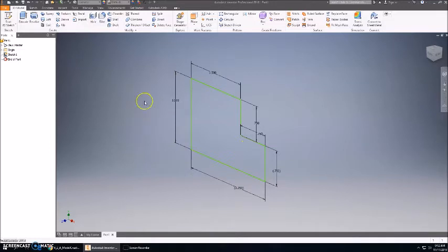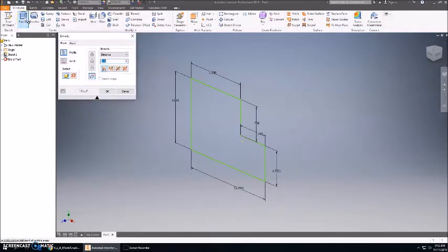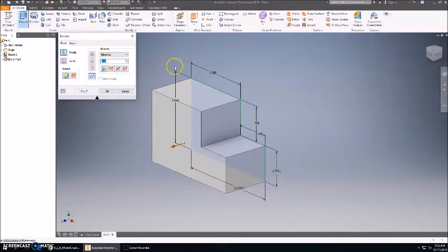So we built the layer of the cake. So we baked our cake. This is just plain cake sitting there, no icing. When we add a feature to it, it's like we're adding icing to the cake. So I'm going to hit Extrude, and that automatically identifies my sketch as, hey, this is an object I can pull out into the 3rd dimension. So I'm going to change my distance to 0.75.